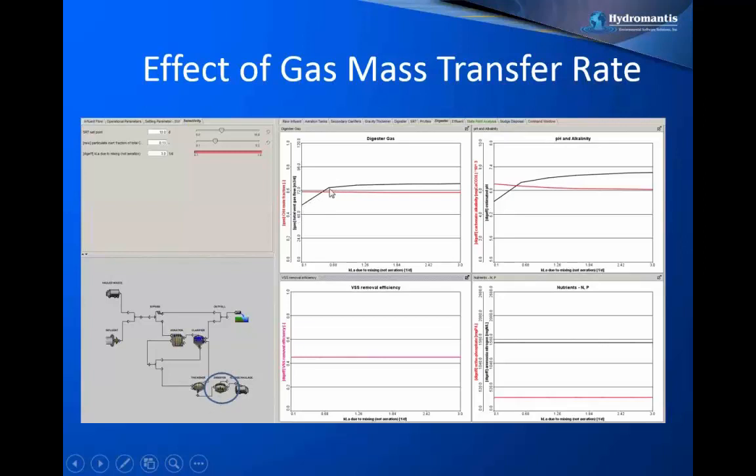That's why, if our mixing is not great, biogas production is probably the same, but what comes out in the gas phase is reduced, and as we increase the mixing, more and more gets stripped out. Also, when more CO2 is trapped in the liquid, our pH is in a lower range, and when we strip that CO2 out, the pH tends to increase.